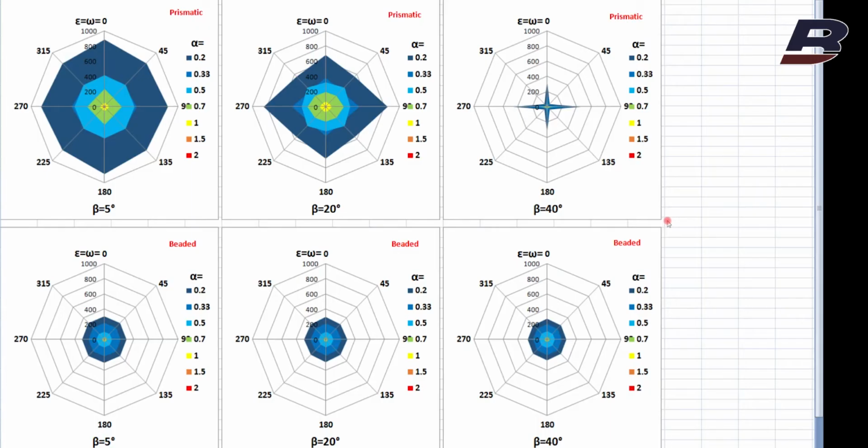We can also observe this phenomenon by performing measurements of coefficient of retroreflection at different orientation angles for two types of retroreflective materials. I've chosen a 45 degree step for orientation angle, but you can perform your own measurements at 30 or even 15 degree step to get more precise data. Check it out.